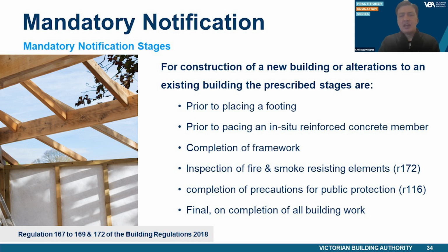Mandatory notification stages are critical stages when the building work must be inspected, allowing inspection of the core components of the building work to ensure compliance with the Act, regulations, and the building permit. Inspections occur at certain stages of the building work, as set out in Regulations 167, 168, 169, and 172. At each mandatory notification stage, an inspection must occur in accordance with Regulation 171.